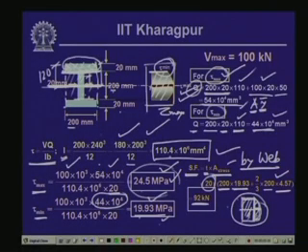Hence, 92% of the total shearing force is being carried by the web. It is interesting to note, as we had seen earlier, that this section is really effective because the top and the bottom rectangles, which we have called flanges, are effective in carrying the bending stress, whereas this web is quite effective in carrying the shearing stress, because 92% of the shear force is being carried by this particular web.